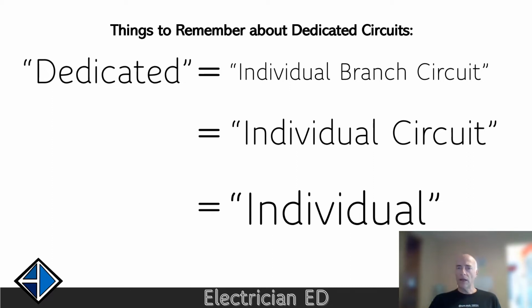In this video, again, I'll be using the terms individual branch circuit and dedicated circuit interchangeably. It's worth noting that oftentimes electricians will use terminology loosely. And I think by the end of this video, you'll know the difference, and you'll realize that if someone says that they're bringing a dedicated circuit to a bedroom, they don't mean they're bringing an individual branch circuit to it with all of the outlets that are in that bedroom.